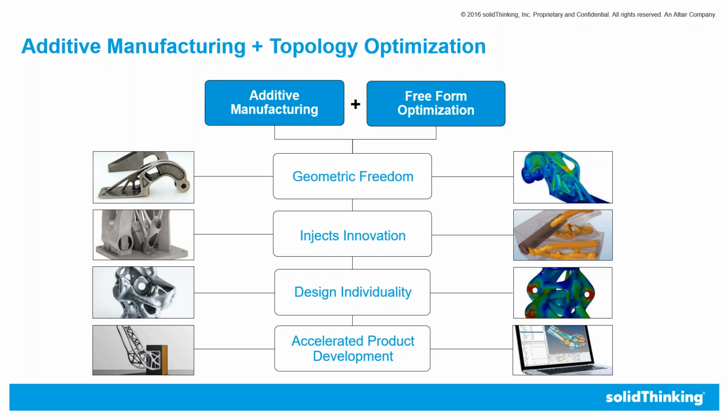And the most important thing is, let's say I'm designing only one or two components, especially working with aerospace or space components, like the one on the left hand bottom side of my screen. This is actually an antenna bracket on a satellite. Only two of those are ever manufactured. If you go the casting way, of course, it's going to take a long time to manufacture, and it's not cost effective. Instead, we go the 3D printed way, which can be done very quickly, can be analyzed very quickly, and is ready to accelerate the product development cycle in that sense.